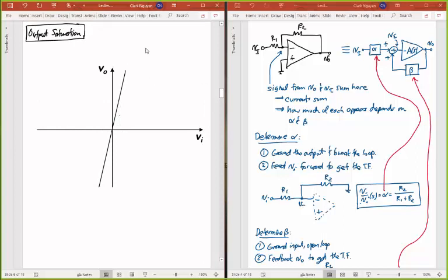There's my op-amp transfer function. And when I talk about op-amp saturation, what I mean is that there are limits to how much voltage an op-amp can put out. And so in this case, I have V out versus VI, and let me show you what I mean by that by drawing the op-amp. Okay, so if this is the plus terminal, that's the minus terminal. Then VI I can specify as this. This is my output voltage. Of course, you know that's going to be equal to some kind of gain. In this case, I'm ignoring frequency effects, so I'll just call that A0 times V plus minus V minus here, which is my input there.